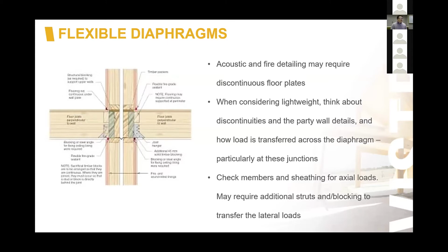It's also really important to check the members and the sheathings for any actual loads. If there are quite high loads inside the diaphragm, they may require additional struts and blocking just to transfer those loads to the bracing elements.